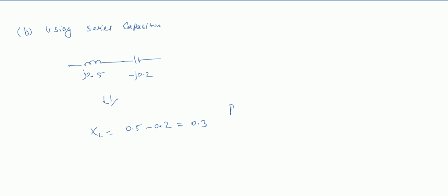So obviously the power transfer will increase, right? So in this way we can increase the power transfer capability. So this series capacitor thing is known as series compensation of the transmission line. Okay, this is known as series compensation, connecting a capacitor in series.